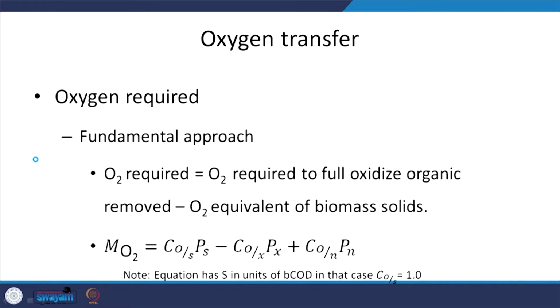And the next aspect, as we discussed briefly, was oxygen transfer. Until now, we looked at the concentration of microbes that we need to maintain, how much time the microbes have to spend in the system, which is the solid retention time, right, and the design variable, which is the concentration of our waste, or the food to the microbes, or the substrate leaving the system, right. We looked at these aspects in different contexts.